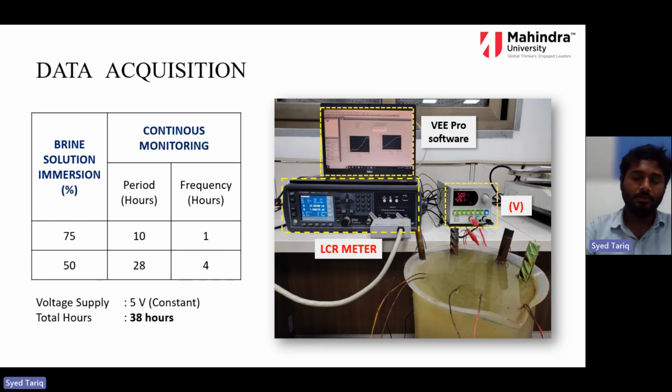We can see the LCR meter is connected to the PZT sensors, and it is also connected to the vPro software interface through a computer, so that we can acquire the conductance data of the structure of that material or element to which the PZT sensor is bonded. The susceptance is used to diagnose the PZT pads you are using, which gives the health condition of the PZT sensor.